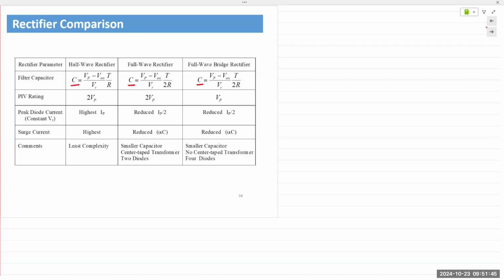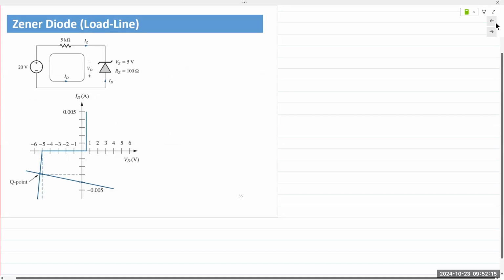So real life supplies, as I stated, this is simply the first few steps. There are a lot of other components that go into making a reliable DC supply. One of the easiest things we can do to obtain a near flat DC line is to add a Zener diode at the end, meaning after the capacitor is done its filtering, we add a Zener diode in parallel with the capacitor to hold the output voltage constant. So the next topic which we are introducing is the Zener diode.